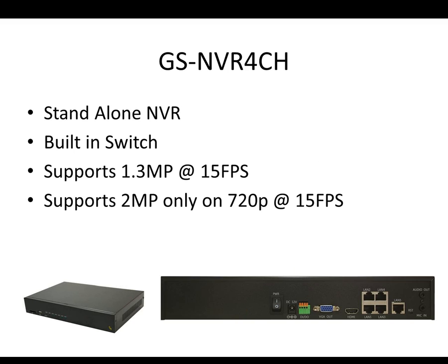We do have a standalone NVR. This NVR has a built-in 4-port switch. It supports our 1.3 megapixel cameras at 15 frames per second. It does support 2 megapixel cameras, but you would have to lower the resolution to 720p, which is 1280 by 720.